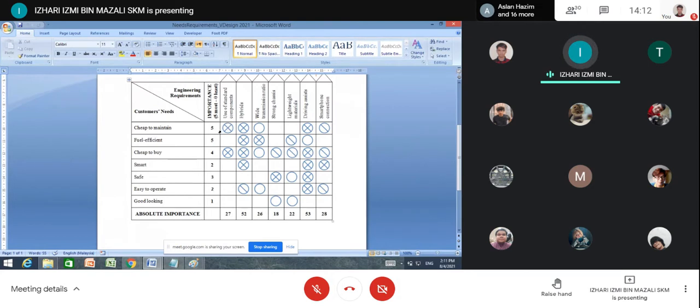The possible driving modes are: one, conventional mode, which means the driving is achieved only by the engine. The second is the mixed mode, where the driving is achieved using the power from the engine, conventional, and also the electric motor. And the third one is the EV mode, which means the car is driven solely by the power from the electric motor. So in this case, you can use the 3 modes as the design target.